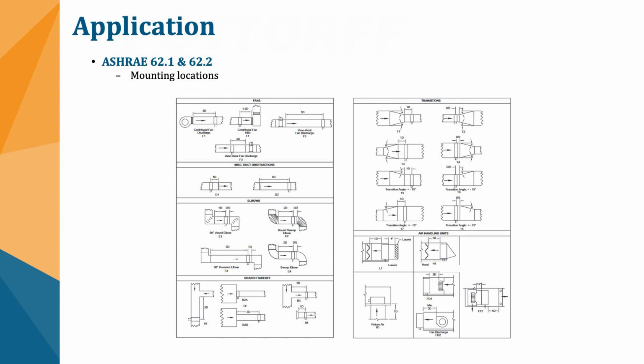And there are different duct devices that have certain requirements that create turbulent air. If you're at the outlet of a centrifugal fan, or in between different elbows or a certain distance away from certain elbows, there are going to be guidelines as to where these more specific airflow measurement stations can be mounted. The reason for that is the only way to get a decently accurate measurement is to have laminar airflow.